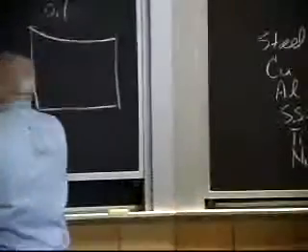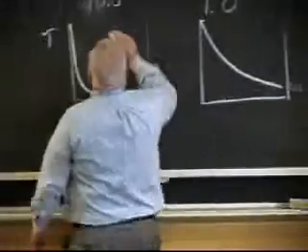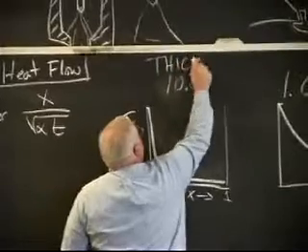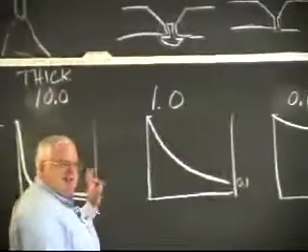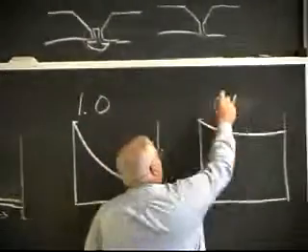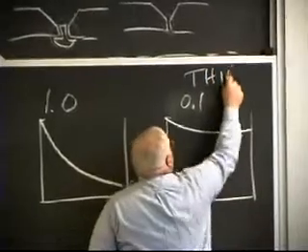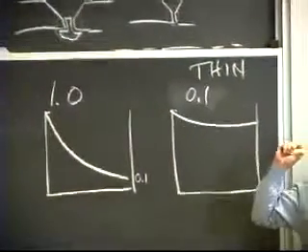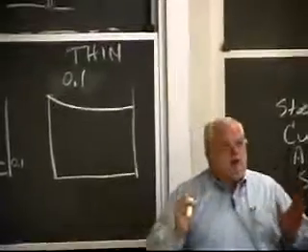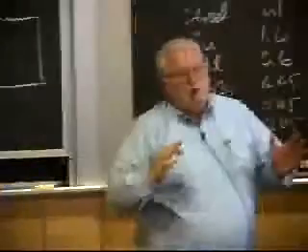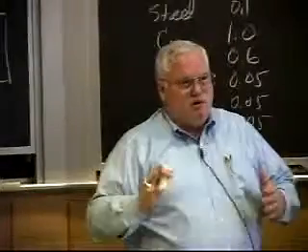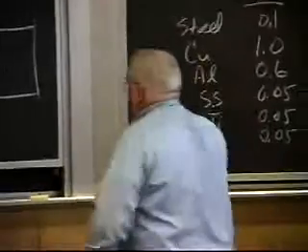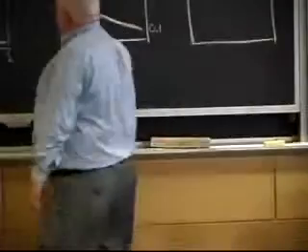Okay. So here I have something that is thick with respect to the time that heat's flowing, and in here I have something that's thin. And essentially the heat has plenty of time to flow through the body because it's relatively thin, compared to the time and the thermal conductivity of the material, which are the only three parameters in the Fourier number, right? So you have three conditions.